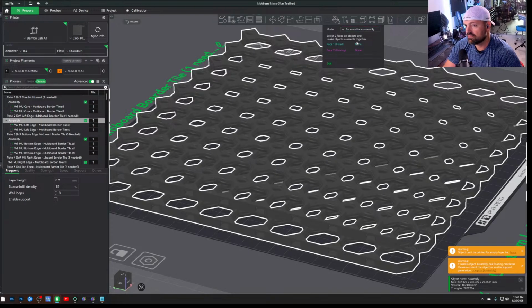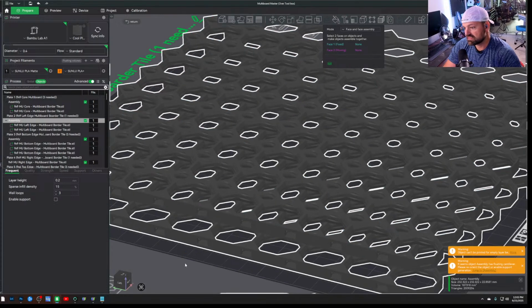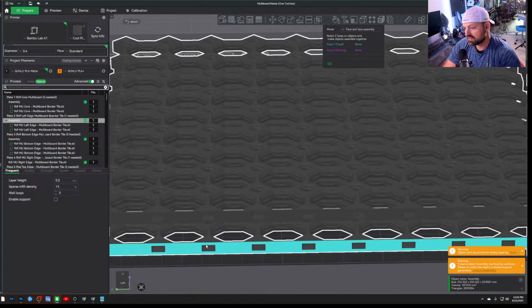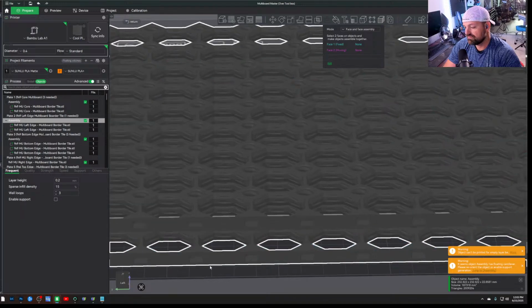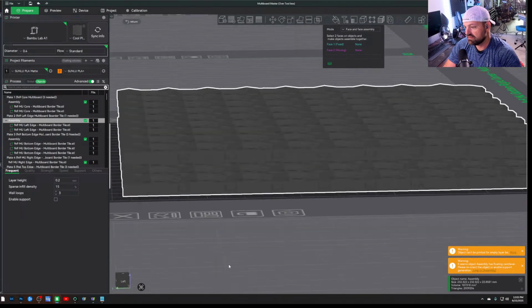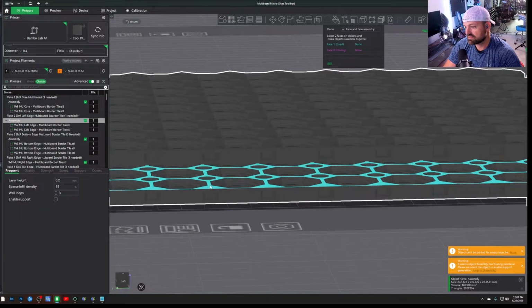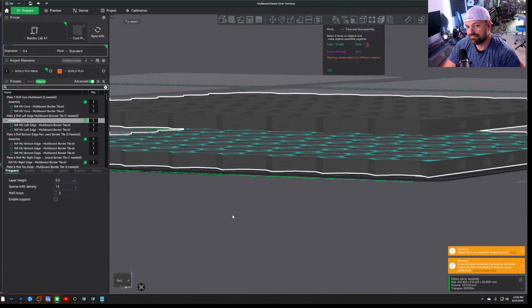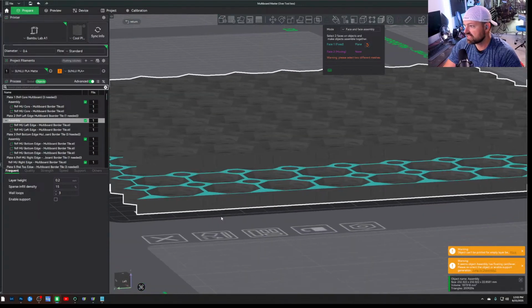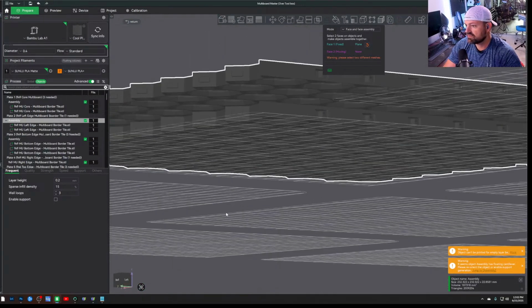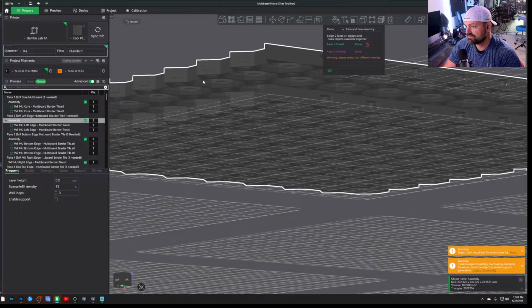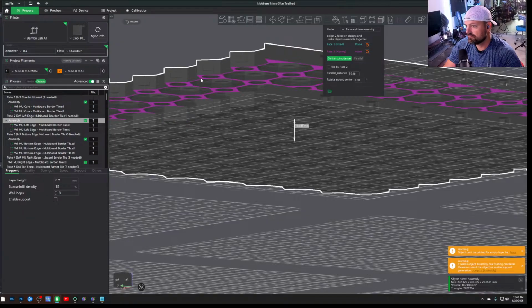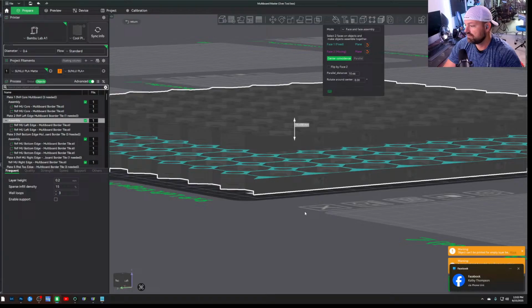Now you have this blue one here, which is the first face, which is going to be the fixed face. So that's the one that's not moving. So you want to pick this, okay? And blue, it's going to highlight, there you go. Should be able to see it. The second one is going to be the pink, and that's going to be the one that moves to it. So we want there. Boop. All right.